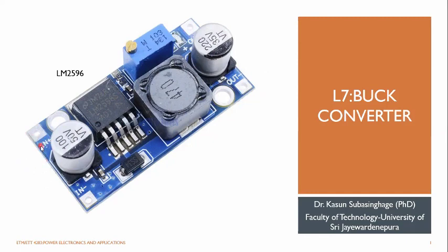This is the control IC of the power supply, which has all the control circuits, and this is the inductor. You need an inductor for these switch mode power supplies, and you need some additional filter capacitors, the output capacitor and input capacitor, and this power diode. There are also some small feedback resistors and capacitors. Sometimes you can buy this controller as an adjustable version, which means by changing this voltage, you can change the output voltage to any desired level.